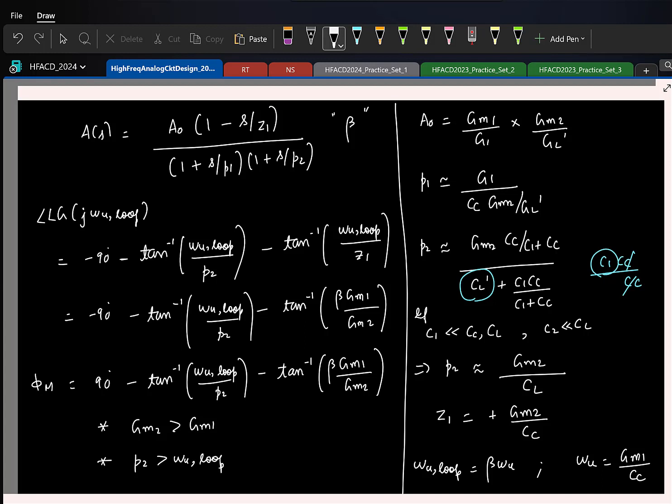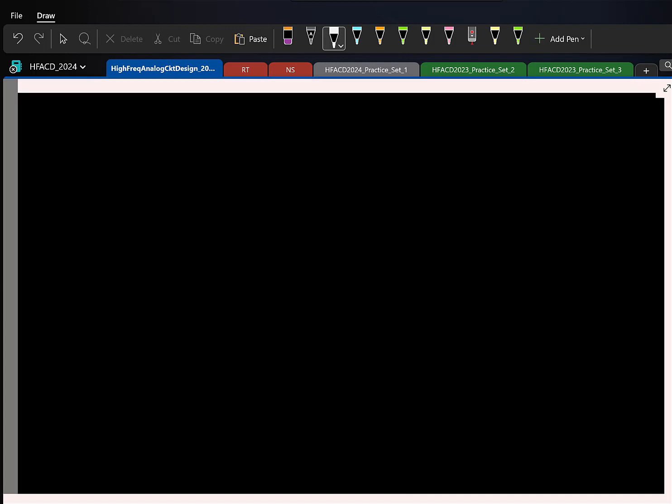And you choose it based on the required phase margin. And in a couple of classes back, we saw that you typically choose phase margin based on two criteria. One, let us say you want fast settling, then you make sure that the closed loop poles are at critical damping. Basically, in closed loop you have two poles. You want them to be on top of each other so that the settling is fastest. So that again I'll give it as an exercise, the phase margin corresponding to that will be 76.